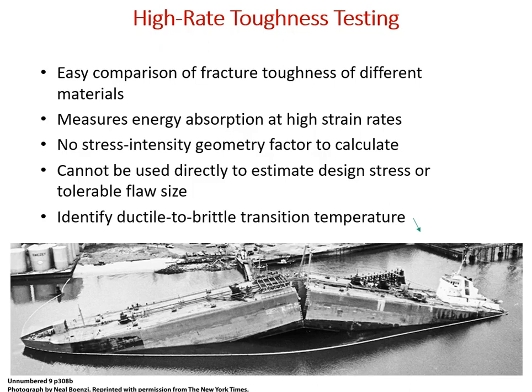Okay. High-rate fracture toughness testing, or high-rate toughness testing. This is an easy comparative test of fracture toughness mainly for different materials or for the same material tested at different temperatures. So we'll measure energy absorption at high strain rates. This is actually a true energy balance method in the case of both Charpy and Izod. It's a very old and elegant test.